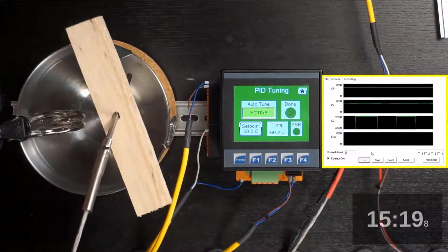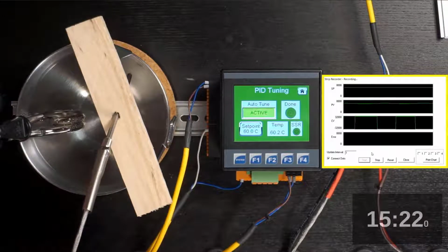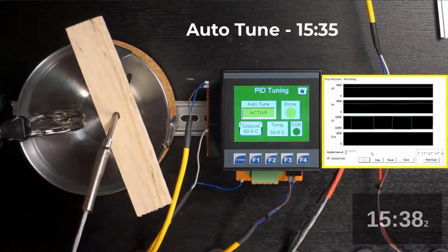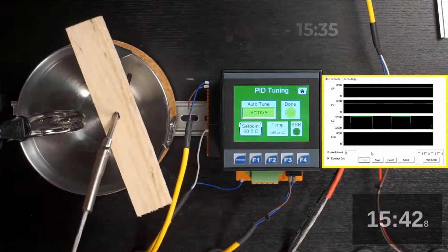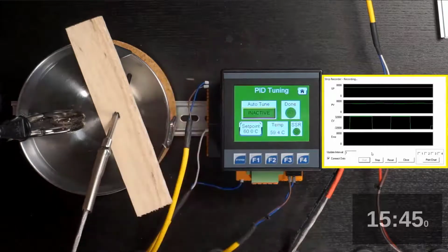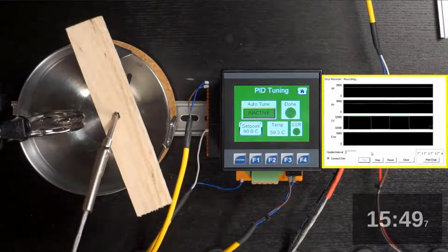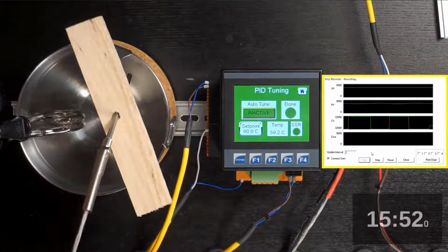Okay, this is our last cycle and we're on our way down. As soon as we get below the set point by 2 or 3 tenths, the auto tune should be complete. And it is. You can see the done bit come on. Now as soon as I turn off the start auto tune button, you'll see the done bit goes off as well. Okay, all right, so that's auto tuning.